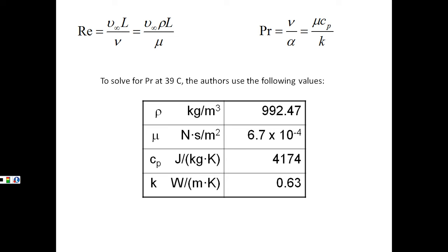And really, the way that they like to define this is how much energy does it take to jack up the material by 1 degree Kelvin? Okay, and so when you see the units, that kind of makes sense, right? It's joules, it's energy being applied versus kilograms, so it's per unit mass per Kelvin. So it's saying, in order to raise that 1 degree, I need how many joules in order to do that. And then our thermal conductivity, we've seen over and over again, is going to be watts per meter Kelvin.